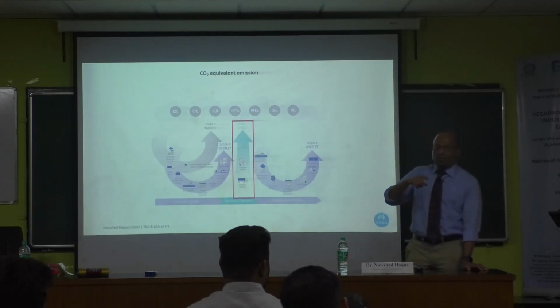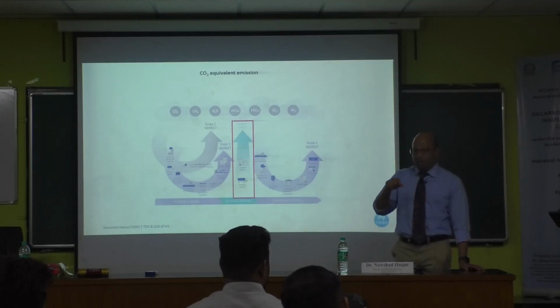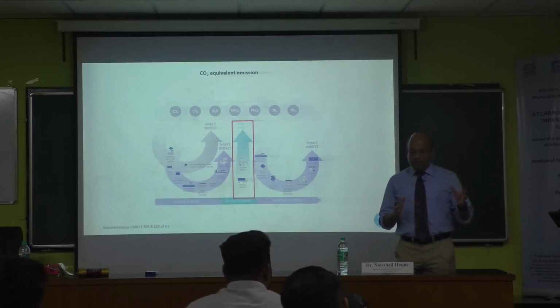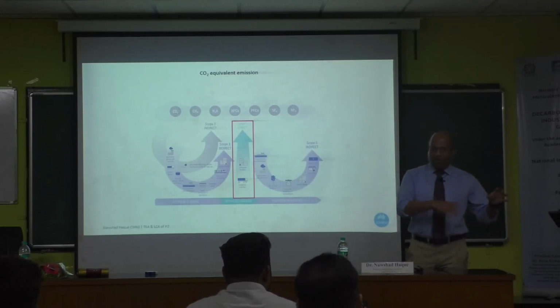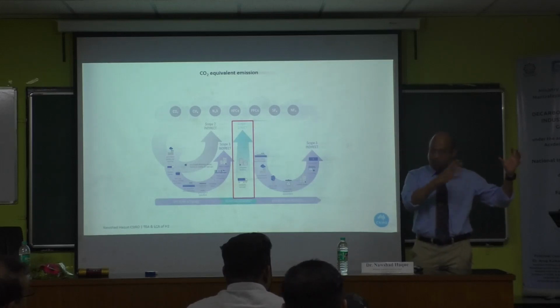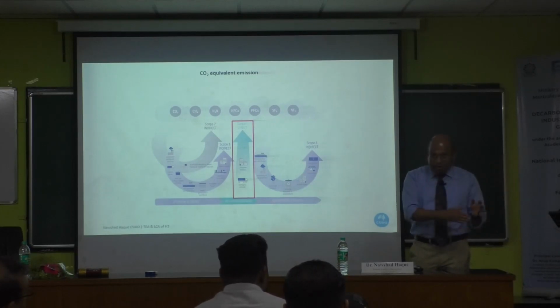So we looked at kilograms of CO2 per kilowatt hour of energy sent out from nuclear. And definitely it is small. But it depends on the uranium, because with poorer grade, low grade ore, which is happening now because the good grade is going onto the market, you do a lot of upstream processing and mining. So in that analysis, if it is super low grade, it would be similar to gas. That's number one, the CO2 point of view.